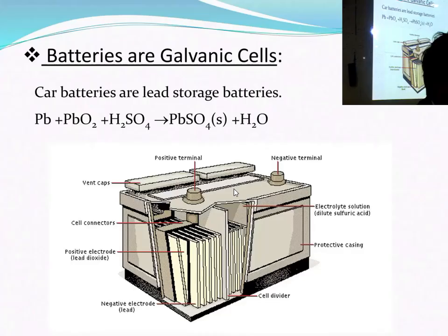If you go for charging and discharging, slowly some of the powdery material like PbO2 falls down to the bottom, that you cannot avoid. That is physical damage. Slowly it gets deposited at the bottom. So up to 5-6 years there will be no problem. And then the quality goes down, meaning performance goes down.